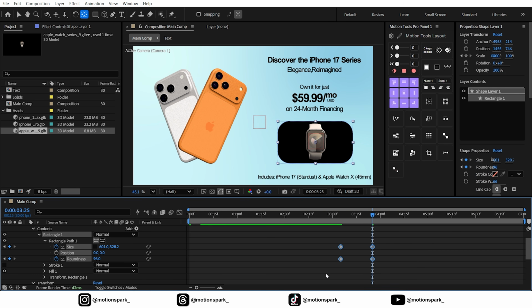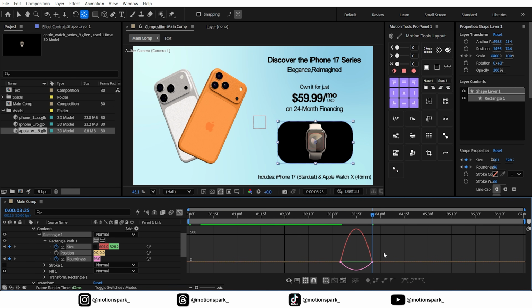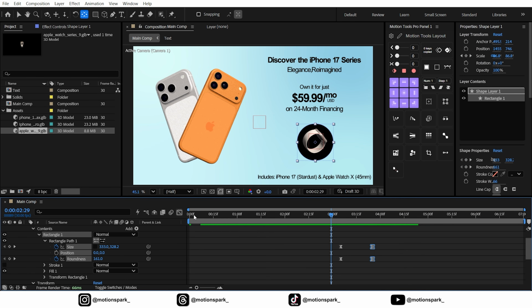Now, select all these keyframes and press F9 to apply easy ease. Finally, let's open the graph editor to adjust the speed curve and smooth out the motion. To make the timing look even more dynamic, let's select this latest group of keyframes and shift them slightly forward on the timeline.